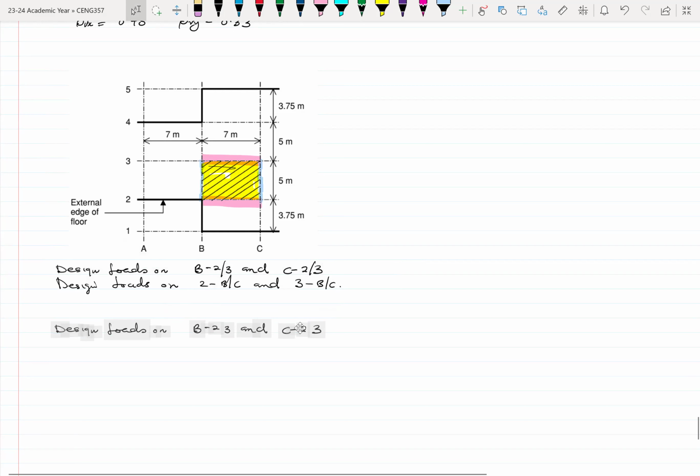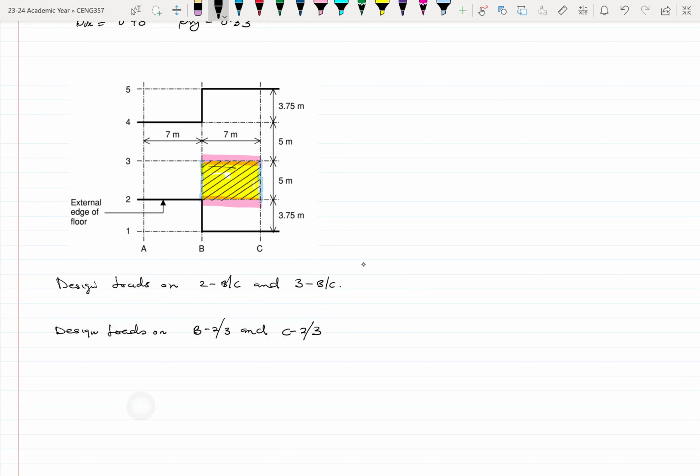Let's take this over here, bring it here for now. So that I just have to do this. Okay. So here for this, my Vsx will be 0.43 times n, which is 14.2, and then our Lx is 5. So this will give us 30.5 kilonewtons per meter. All right, again, we are dealing with per meter width.